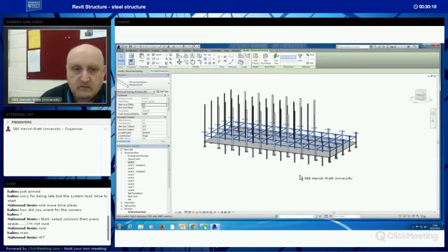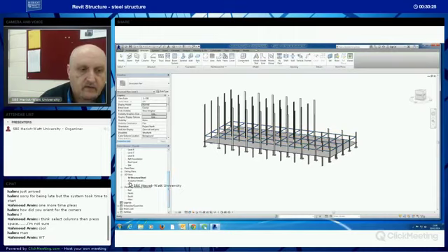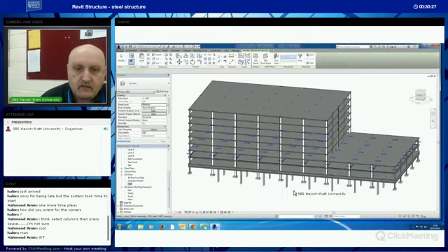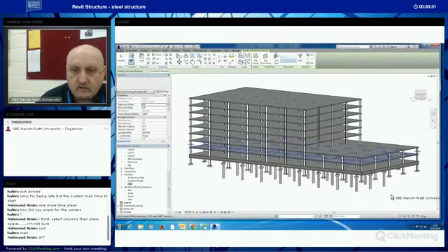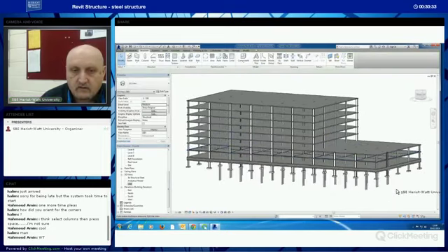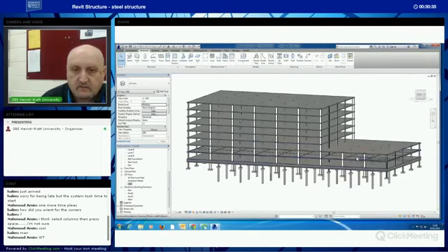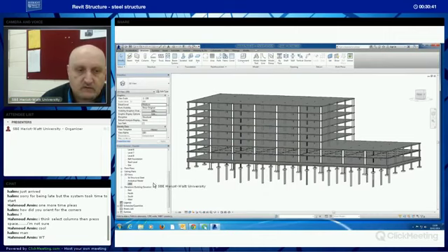These beams support the floors, they don't occupy the same 3D space as them. So if I were to look at that in the default 3D, you can see they're actually intruding upon them, you can see through them. That's clearly not what should happen. The beams, the structural framing, should be underneath the floors in order to give them the necessary support.